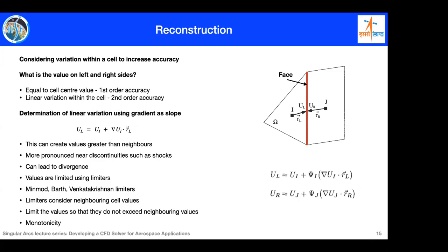I have a question. Do you know of any commercial codes that actually make use of artificial dissipation type of methods? What I know is that in commercial codes, they will use one of the schemes, but they will also add some additional dissipation. Even in CFD++, there is one tuning coefficient, with which you can add or tune the dissipation. This is over and above the scheme. So it is a kind of artificial dissipation, not in exactly the same form, but it will add a certain amount of additional dissipation over and above the scheme.